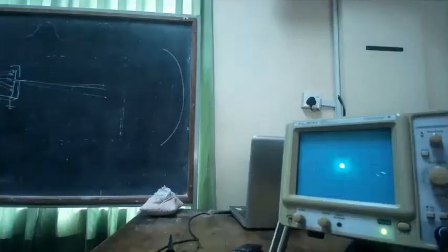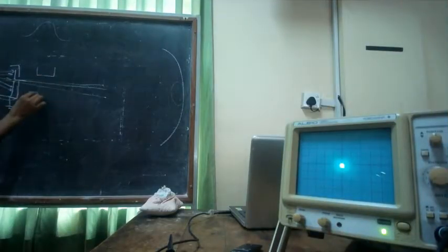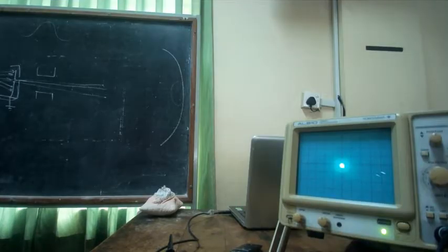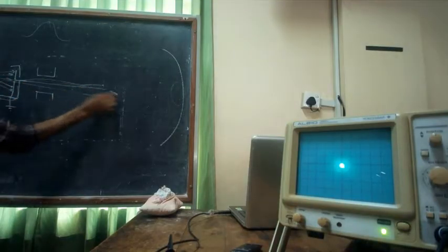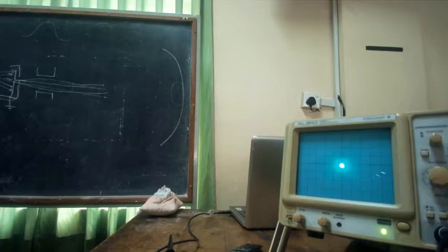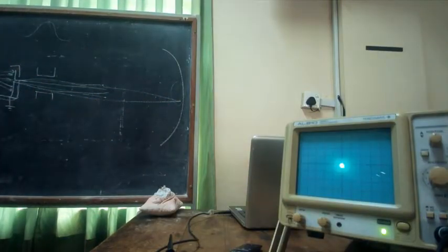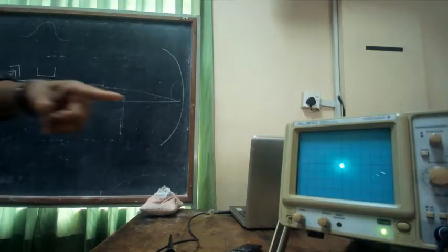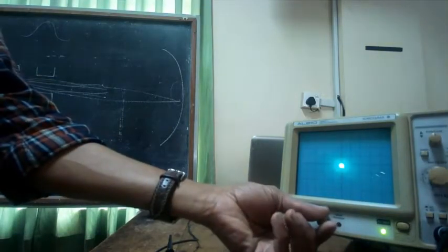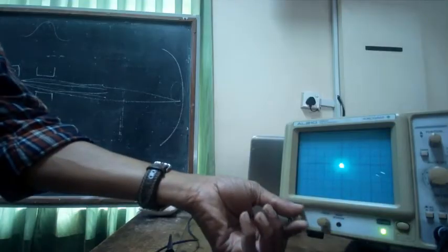This is done by applying another electric field, a negative electric field, so that it bends the beam like that. So this is called focusing. If you have a negative electrode here, what happens? It will repel the electron, right? So it basically bends the beam, and by controlling the voltage, you can make a sharp point on the screen, right?